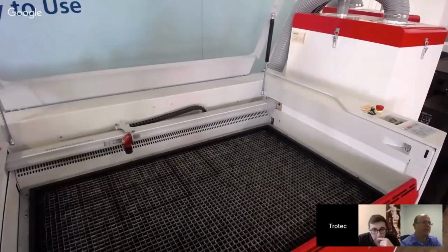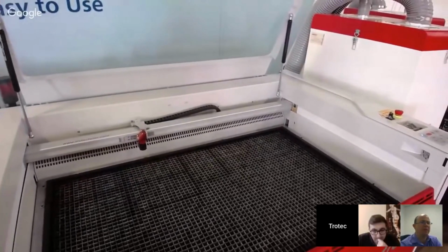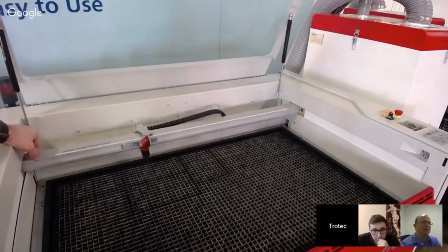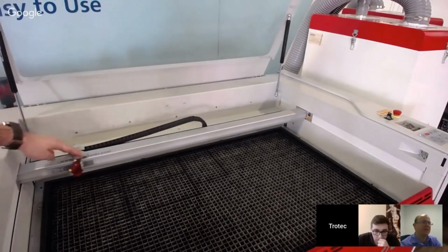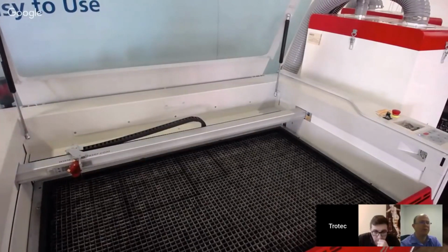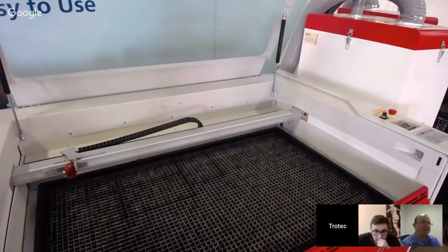So that's how you get that nice white engraving. The only area where I would not run bottom up engraving would be on engraving rubber for rubber stamps. For some reason, the dust seems to clear out of the sheet better when you are engraving top down versus bottom up. I'm not exactly sure why that is. It just seems to be better for airflow when you do it top down on rubber. But for basically everything else, I'd say there's no reason not to do bottom up.